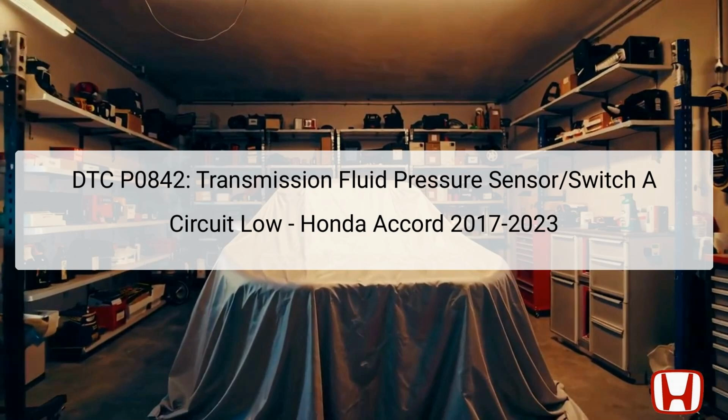The transmission fluid pressure sensor, located typically near the continuously variable transmission, CVT, plays a crucial role in ensuring that the transmission operates efficiently by monitoring the hydraulic pressure inside the system. If the pressure is low, the TCM can adjust various parameters to ensure smooth operation. The error is electrical in nature and indicates no mechanical issues within the transmission system itself.